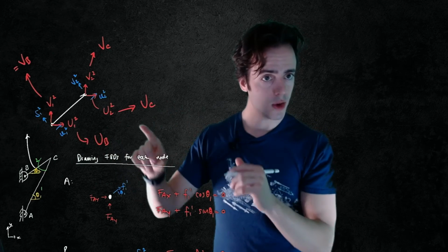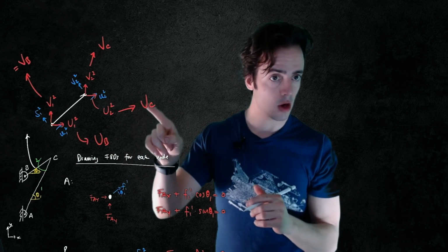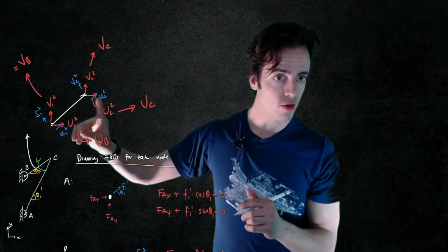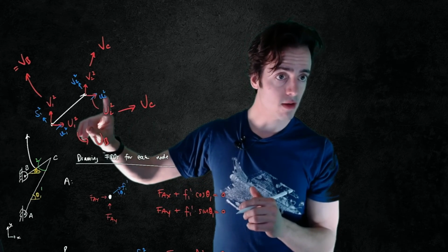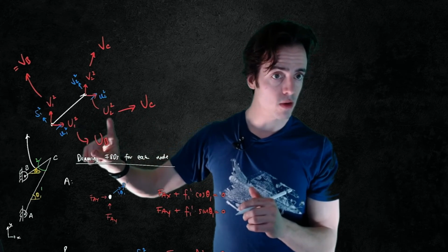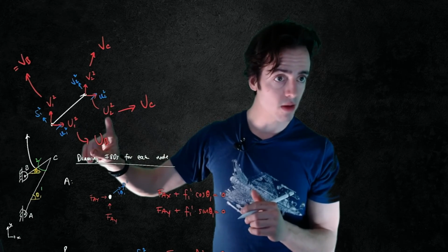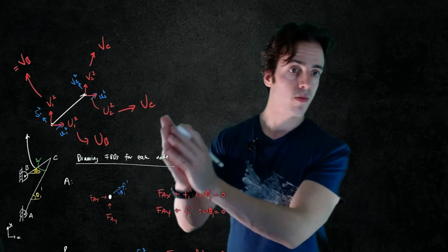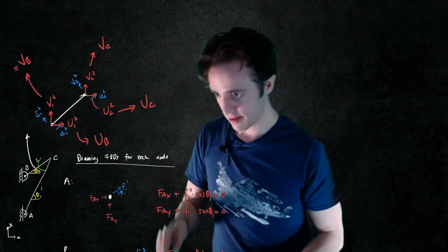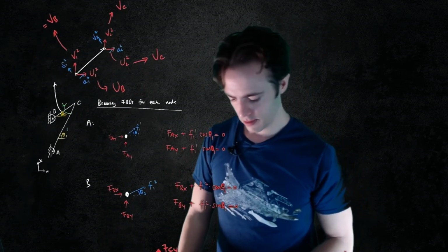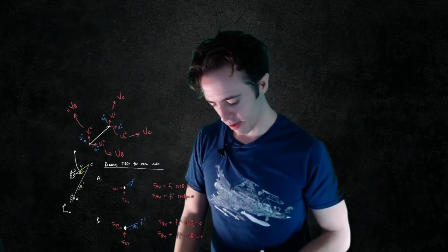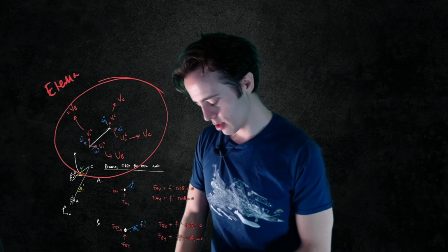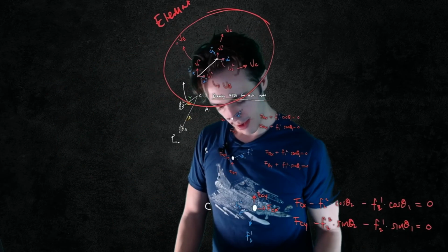So we don't have correspondence between lowercase and global coordinates in terms of nodal displacements. We've got a transformation from lowercase local displacements to these elemental displacements in global coordinate systems, and we can then say that these correspond to these nodal displacements. So let's write out our correspondence in full. We've done this for a single element, element 2. Let's do this for element 1.